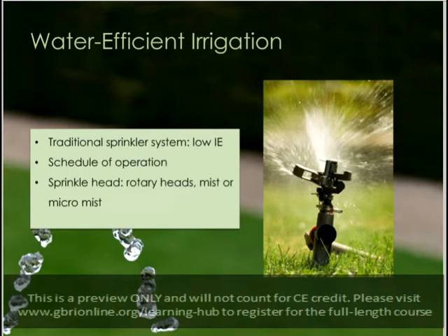Assuming an effective landscape design, the engineer designing the sprinkler system should use landscape zones to determine the placement of sprinkler heads, provide optimum application rate based on soil type, and avoid overspray to adjacent areas. Application rate is the rate at which soil is irrigated in inches per hour. If the application rate is more than the infiltration rate of the soil, runoff occurs.